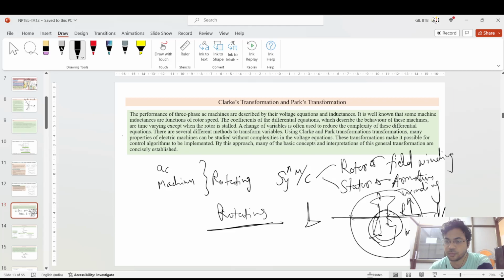This reluctance is more, so the MMF is low. MMF low means the flux storing capacity is low. So the inductance is also low in that system. But in the Q axis, the gap is very low, so the flux can directly transfer, the reluctance is very very low, and the MMF is very very high.